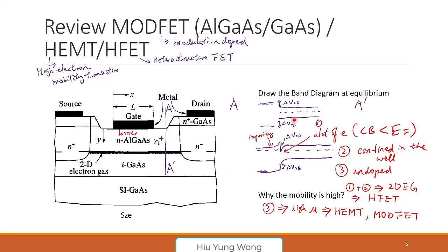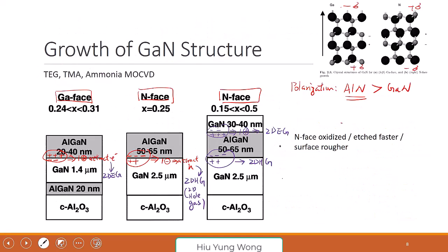But I remind this because later, even in your interview, people talk about RF, they talk about HEMT. Don't confuse it with gallium nitride. Ask them, which HEMT are you talking about? Both of them are HEMT, but they share the same idea. They form a 2-dimensional electron gas at this hetero interface. The only difference is that one gets the formation of electrons by having heavy doping in the barrier, but still high mobility because these impurities are not close to it. For gallium nitride, it gets this high electron density by the polarization charge that we just discussed.